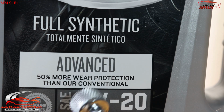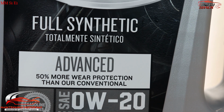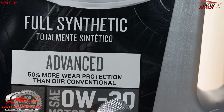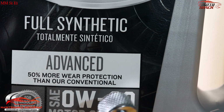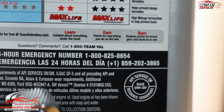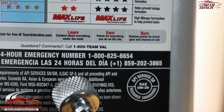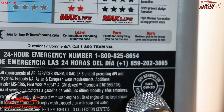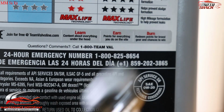This is the winter specification, but you need to check your manual to make sure you are choosing the right oil to start with. That's very, very important. The factor here is really for winter. It would be good to put exactly what is required in it, but if you can't find 0W20 and you can find SAE 20 for your vehicle in Ghana, you can actually run SAE 20 if it passes all the other standards. It needs to meet, like we said, the GF-5 standard or the API SN. If you can find all these things, then you can run a straight SAE 20 instead of worrying about the 0W. I hope this makes sense.